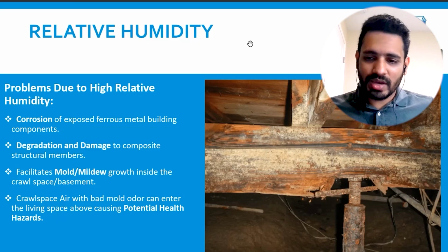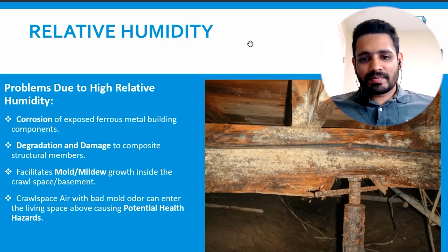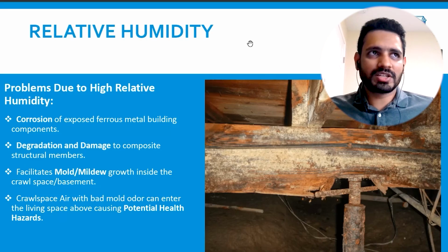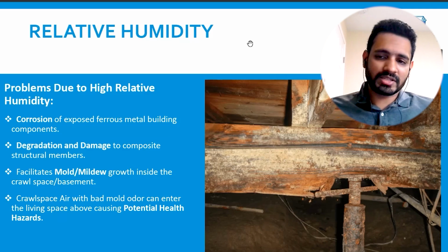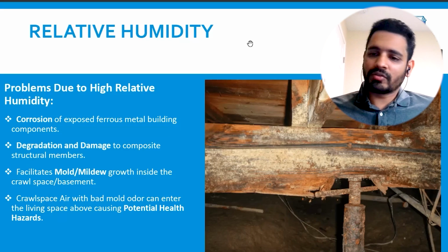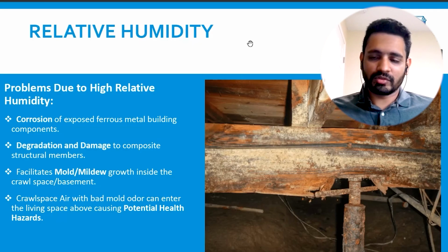So in this case, why did they put a jack in this case? I don't understand. I have never seen a house with jacks in it before. It's usually made from wooden posts. Screw jacks or metal jacks or adjustable jacks, as they're called, or smart jacks, are not uncommon. You see them in 3 or 4 out of 10 crawl spaces. The remaining 6 or 7 out of 10 crawl spaces have wood posts supporting the floor beam.